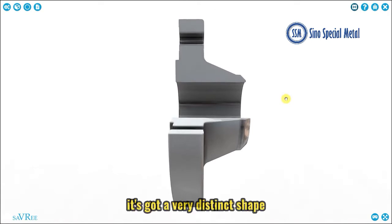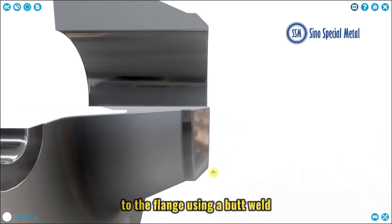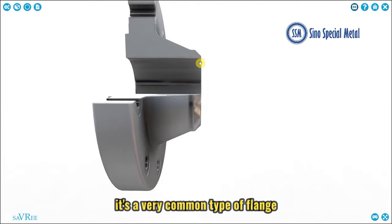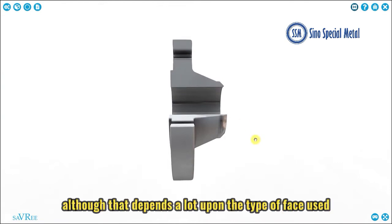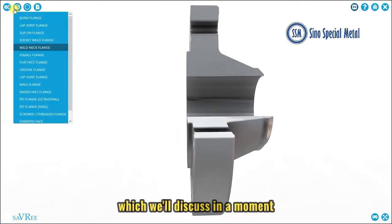It's got a very distinct shape. The hub has this long neck, and we would connect a pipe to the flange using a butt weld. You can see that the flange has been prepared for the weld, which would go in this area. It's a very common type of flange because it's mechanically strong and it's suitable for a wide range of temperatures and pressures, although that depends a lot upon the type of face used, which we'll discuss in a moment.